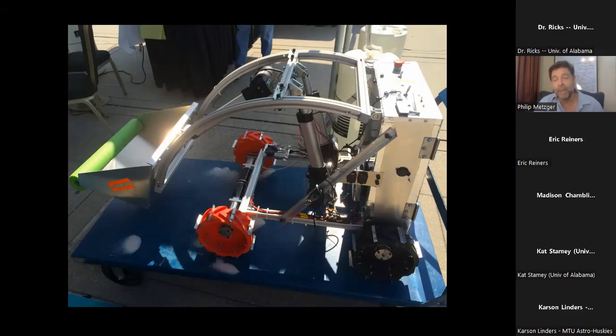And so what happens is the diagonally opposite wheel lifts itself off the soil and reduces its normal force. And when it reduces its normal force, that reduces the shear strength of the soil under that wheel. And so that diagonally opposite wheel begins slipping, and it digs a hole under it too. And you cannot believe how many times we saw this happen. In the first 2 years of the competition, we saw it happening over and over with diagonally opposite wheels digging holes, and then the vehicle is stuck.